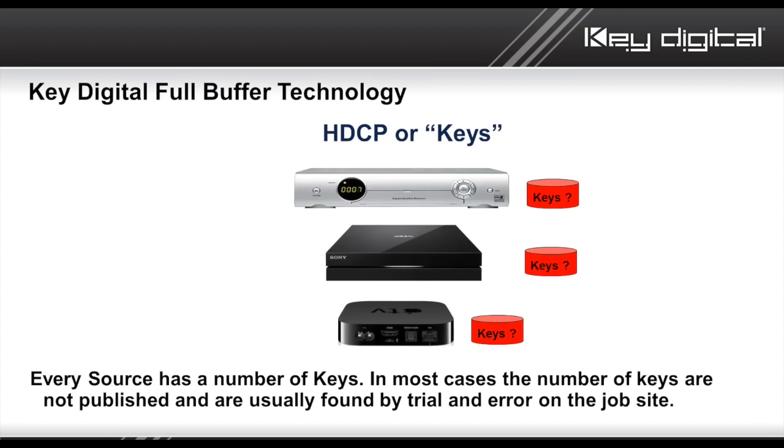of the HDMI signal, which we introduce you to. HDCP. This is the dreaded HDCP, right? Dreaded. Why dreaded? Well, it's a 4-letter word. So has everything else been, though. This is a fact of life now, HDCP. You in the AV world have grown accustomed to HDCP. This was the part that folks really didn't like as the analog sunset occurred and the digital sunrise occurred.